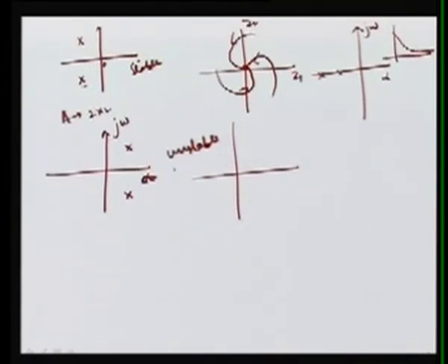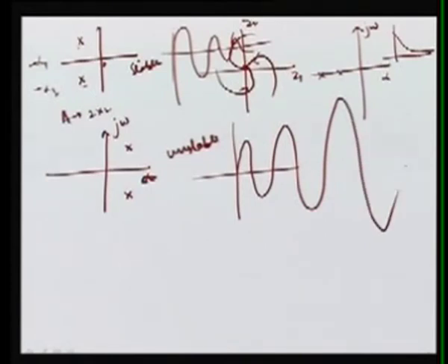But here, if you have this, what will happen? In this case it will be oscillating, and the oscillation will keep on dying down, because the real part is negative, and that is damping. So here we have minus alpha 1 and minus alpha 2 as well. So it will oscillate, but it will be decaying. In this other case there will be oscillation, and it will keep on increasing, and the system is unstable.